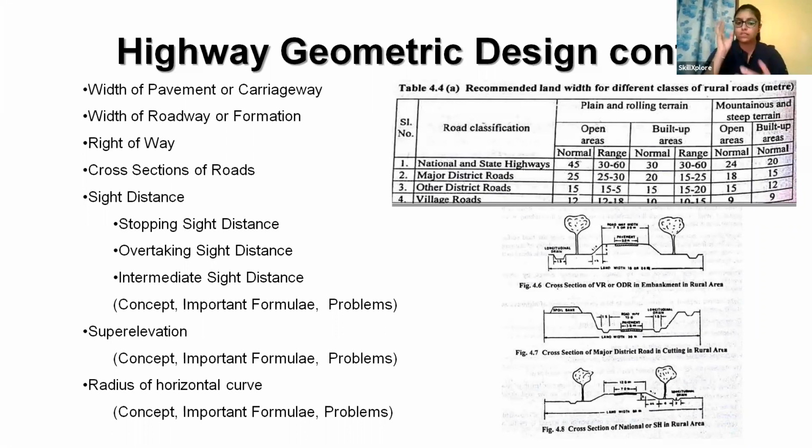You are traveling at the design speed, or the speed which you are expected to travel on that particular road, and maybe the vehicle in front of you will be traveling at a lesser speed. So you are trying to overtake that slower vehicle. In that case, while you are reducing the speed also, you shouldn't collide with the incoming vehicle or the overtaken vehicle.